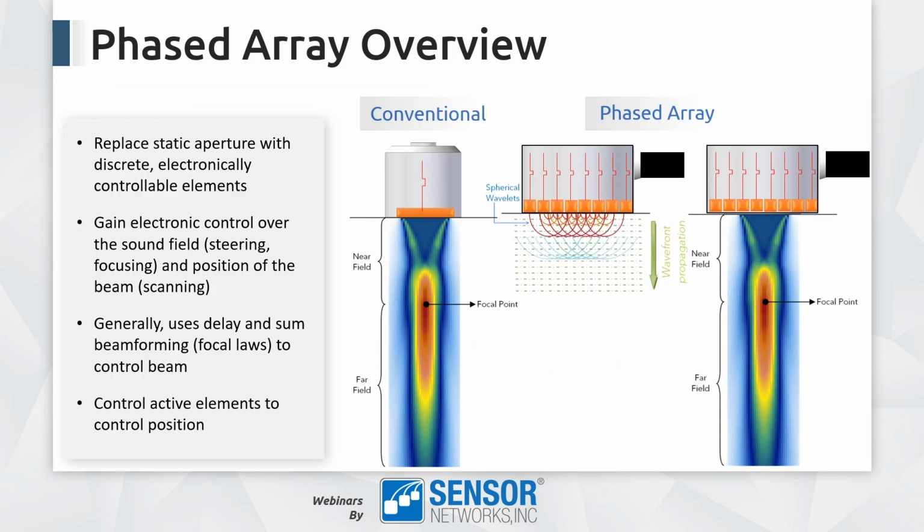So to give you a brief introduction of phased array, the benefit of phased array is that we're trying to replace a static aperture that we would get from a conventionally designed and built transducer with something that's electronically controllable. We do that by taking the piezoelectric material and making, instead of a single monolithic element, many small elements that are individually electrically addressable and controllable.